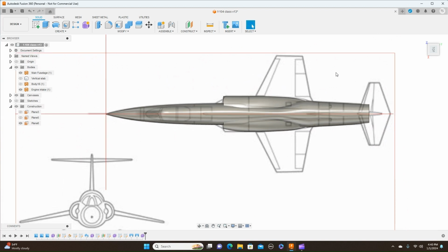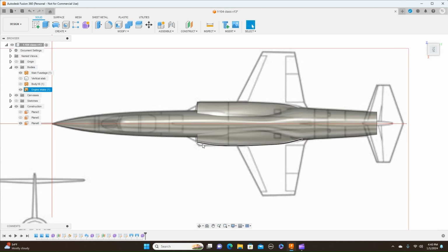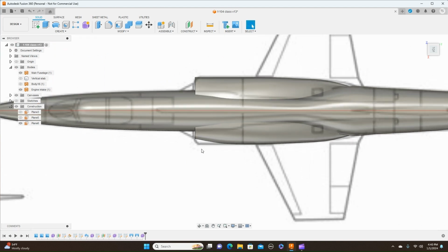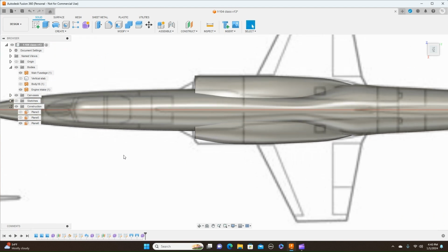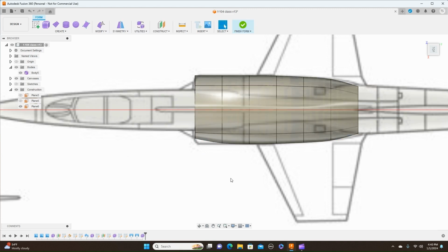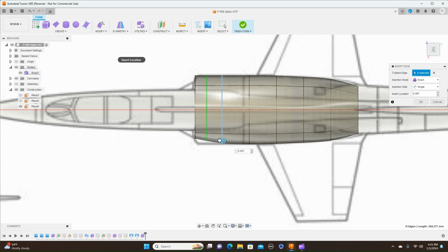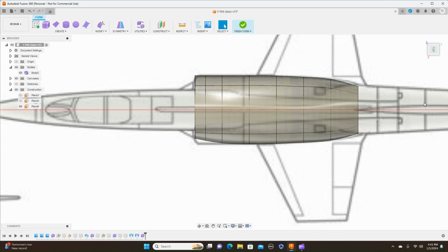Now look at the top here. Now, since I moved that in, now this is in a little. So what I do here, come down here again, edit. Now we don't have a line here to pull this out. So we'll just create one, and you double click on that, go up here to modify and insert edge. And now we have a line there. Make sure this is exact and click OK.